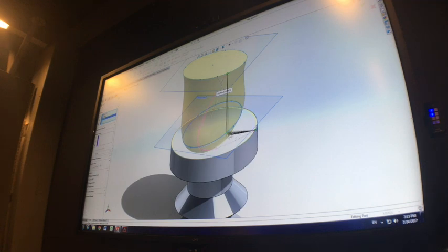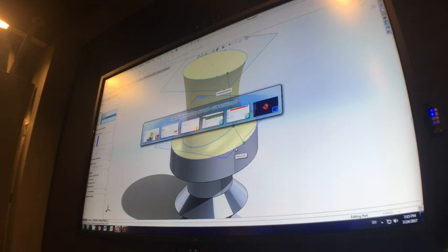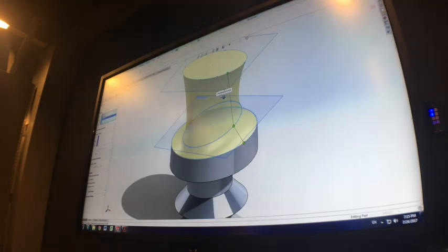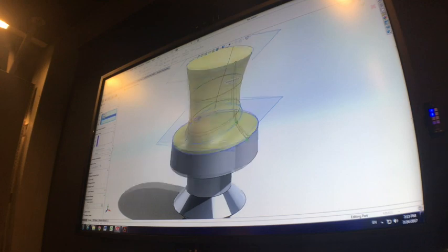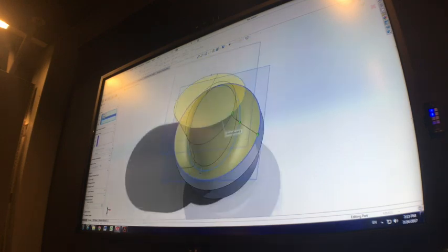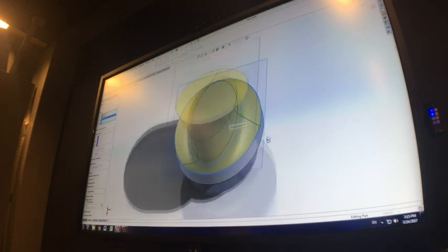So to avoid that, and also to try and get a symmetrical type shape, which is what we're going for, when you're having a look at this, it's pretty much the same both sides, front and back. We want to try and line those up. So there's 2 things we want to do. First, we want to click on curvature display, which is on the properties on the left and towards the bottom, and press mesh preview, and that will bring up these contour lines, or mesh lines. Second, we want to line up those control points.